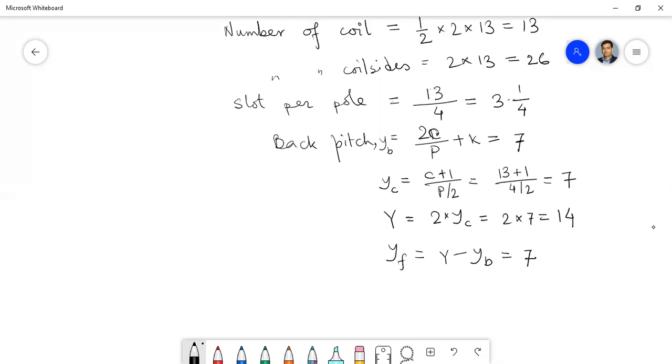Okay, that will not be required for winding as you have seen for this winding table. For the winding table, as we have drawn for the simplex lap winding, the important things are the back pitch and the winding pitch. Commutator pitch also will not come, because the commutator pitch will come only in case of the radial diagram that we have drawn in the drawing sheet, A3 paper.